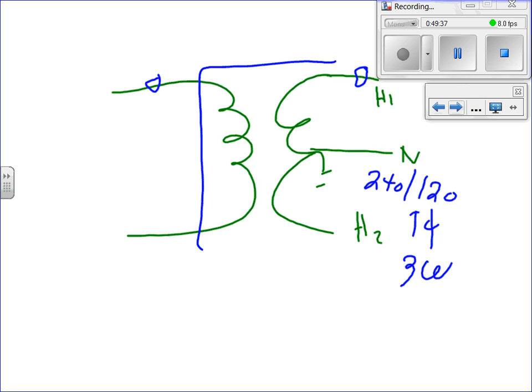And this big fat thing is actually one big thing. On the primary side, how many conductors do I need? What voltage would it be if this is a 3-phase system? Most likely, if it's in your building single phase, it's going to be 480 volt. So this is phase A and this is phase B, right? That's an option. You tap it from one phase. That's what you would do if you have a single phase transformer tapped from a three-phase system.